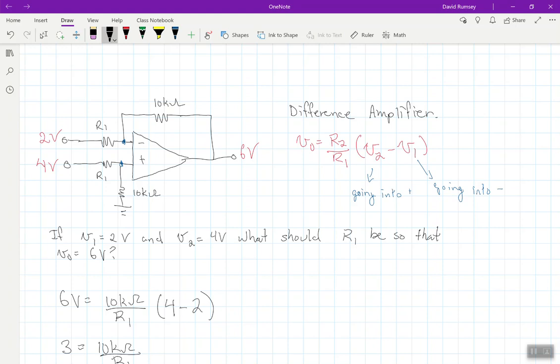And I've actually seen production lines before. Now they have standards in place that this really shouldn't happen, but I've seen it happen once before where they were putting the wrong component in for the assembly of the boards. For instance, I don't precisely remember what the component or the value was, but it was like they were putting a 1 kilo ohm resistor in when they should have been putting a 10 kilo ohm resistor.